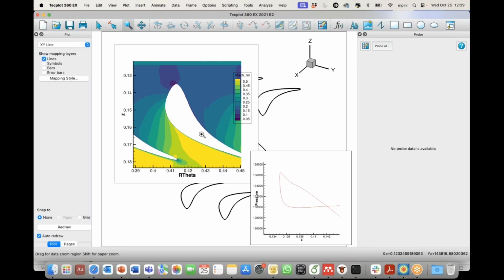So if you don't want to touch the rotor because you think that it matches your mainline design perfectly, what you could do is change, as an example, the inlet metal angle of the stator in order to compensate for this offset.